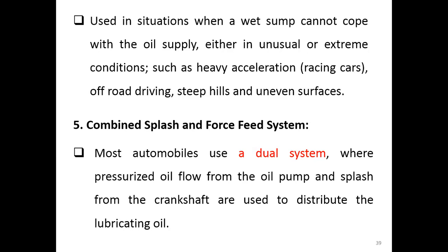Because under these situations, it's very difficult for the wet sump to deal with the oil if the oil is still stored inside the engine. The amount of space inside the engine may not be big enough, especially in a racing car, in which you need a high flow rate of lubrication oil.